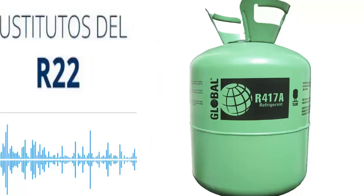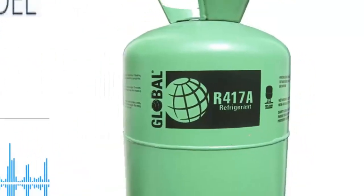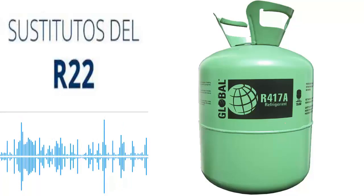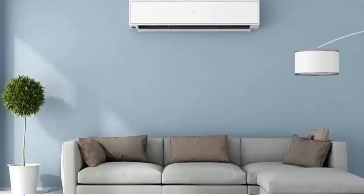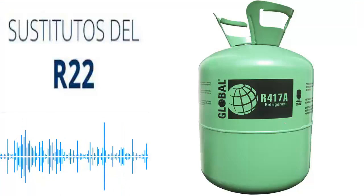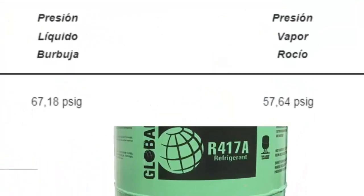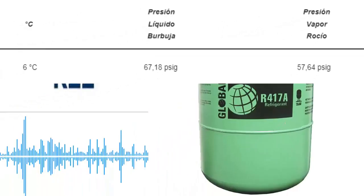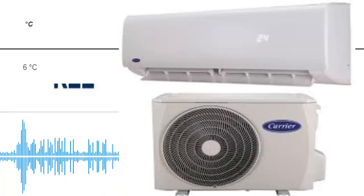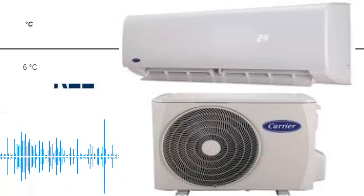In this class we are going to talk about the refrigerant R-417A and its work pressures. The main application of the refrigerant R-417A is in air conditioning systems, chiller type, and heat pumps. In air conditioning applications, it is usually worked with a temperature of 6 degrees Celsius at the exit of the evaporator, which needs a pressure of 57.64 psi. Then, for air conditioning applications, 6 degrees Celsius in the evaporator, we need 57.64 psi.